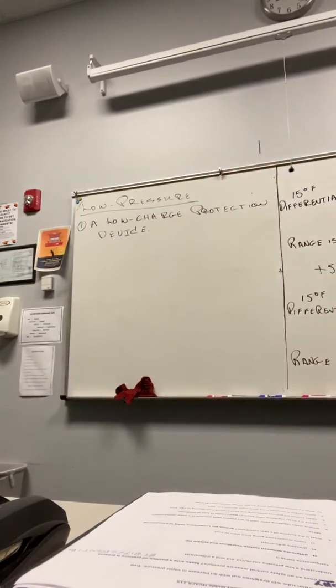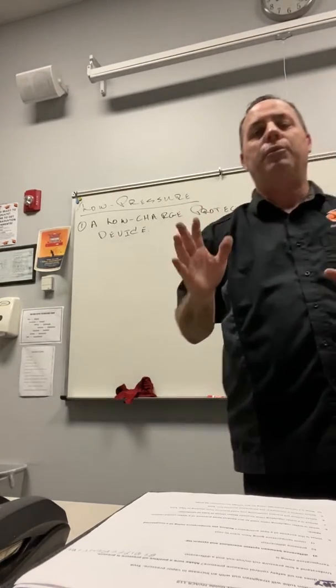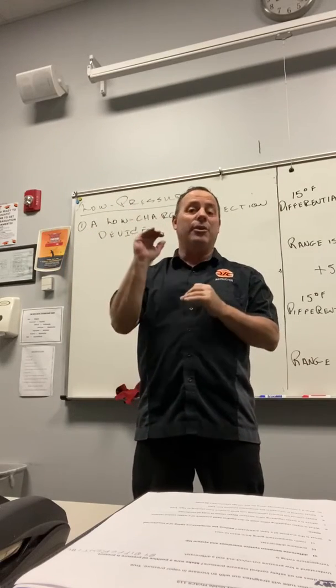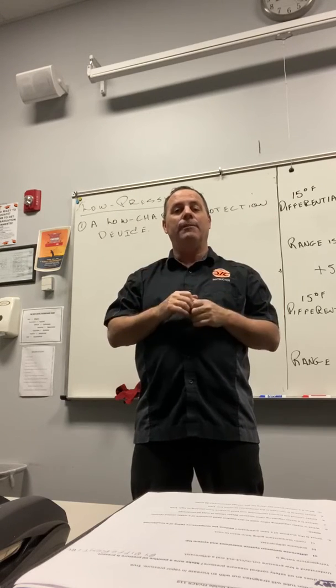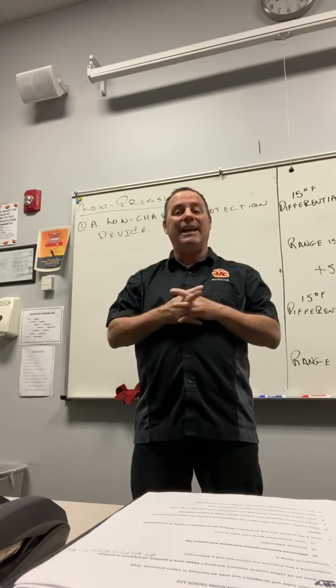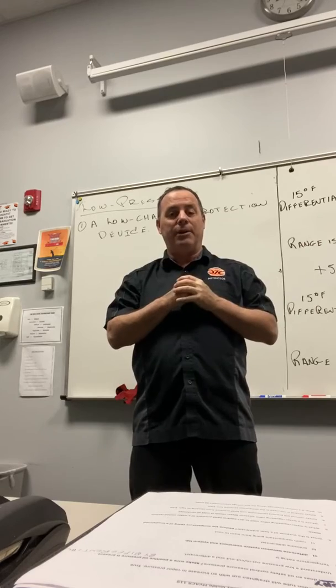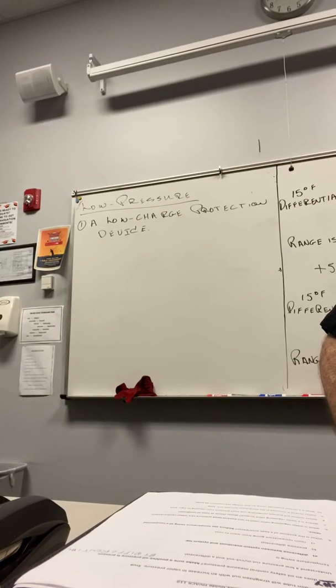And it also says, in commercial refrigeration applications, low pressure controls are also used to cycle compressors on and off in response to evaporator pressures. Now you can use low pressure controls to actually not have a thermostat. You can take the pressure, convert it to a temperature on a PT chart, and know what pressure you want it to cut in and cut out at. And that will maintain the box temperature. That's for another chapter. Right now we just want to discuss what a low pressure control is. Okay, any questions about that? They can be used to harvest ice and all these kinds of things.